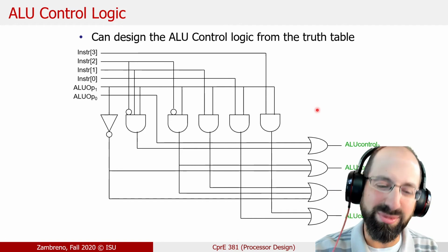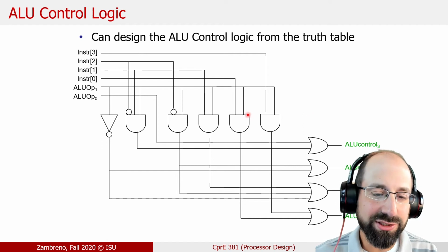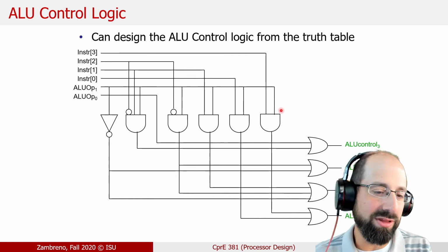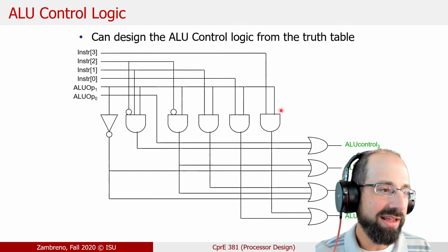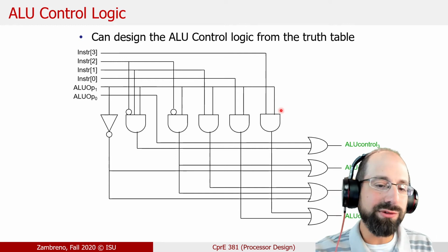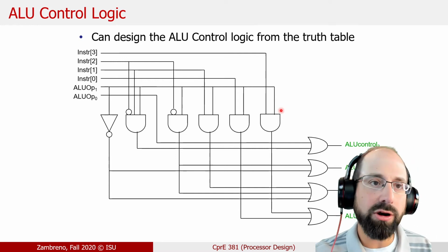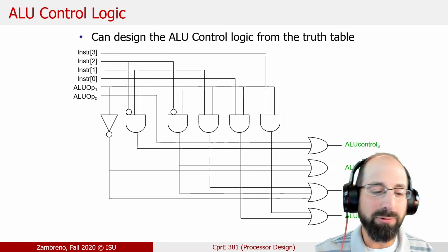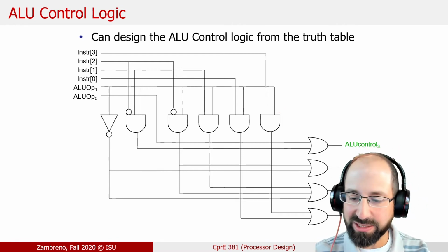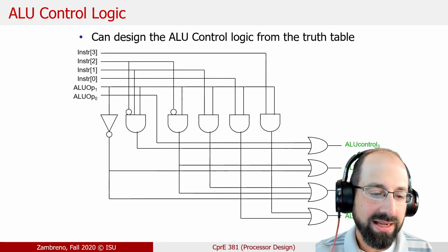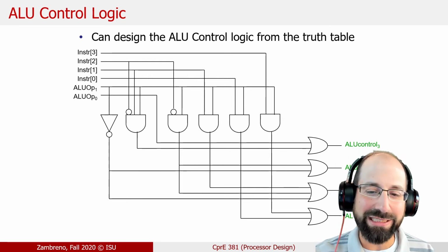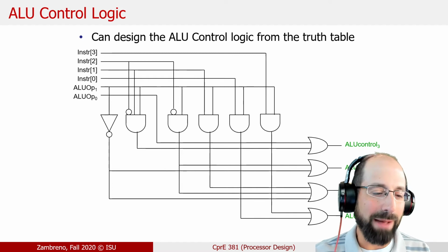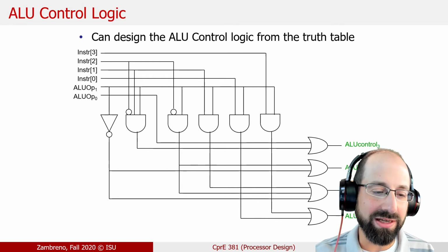And I think that's the smarter approach. This optimization, which is nice, you can really minimize the number of gates required, is also very brittle, right? As soon as you realize 2 weeks into project part B that you actually encoded one of your control signals incorrectly, and what should have been a 0 for this instruction is actually a 1 for that instruction, then you have to go back and re-optimize all that logic manually and get back to a new optimized sum of products representation.